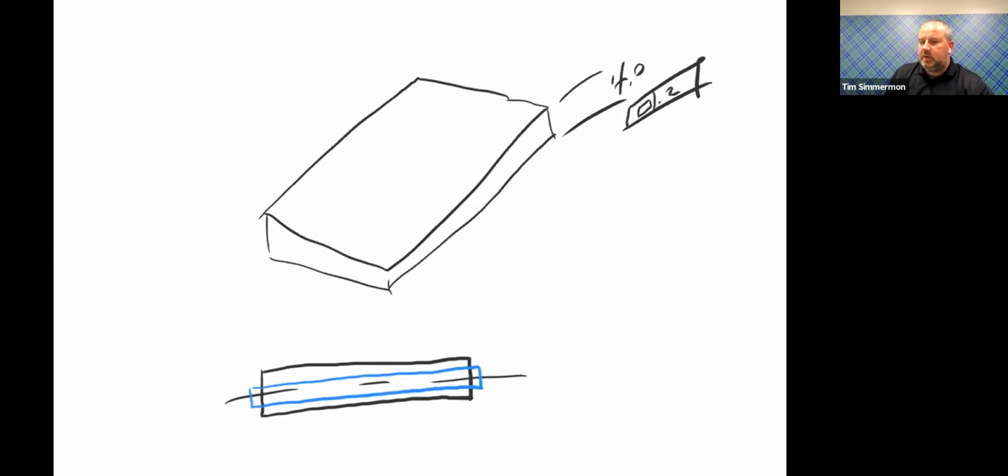And how do you measure the flatness of a theoretical feature? Becomes a bit more different. Now what they're measuring is at every point along this 3D part, and again, I apologize for my horrible drawing, definitely not to scale. The center point of every location from here and here has got to lie within that box.